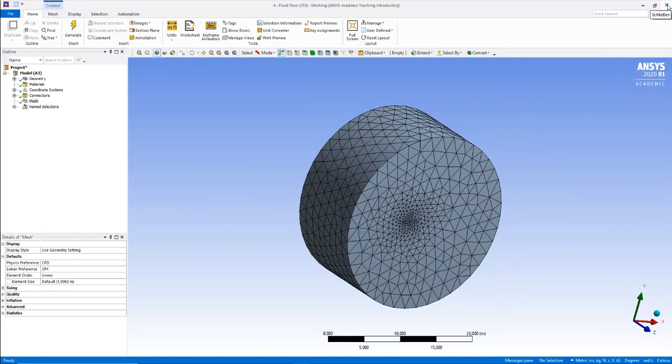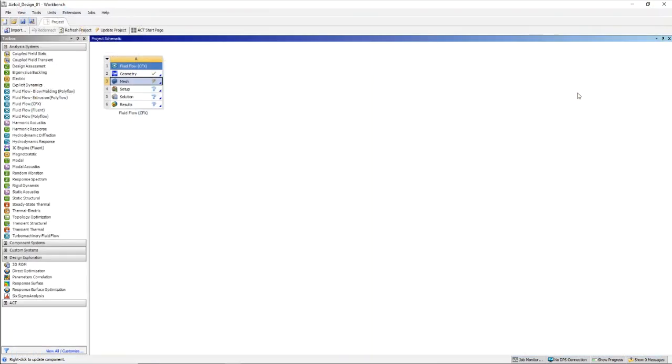Okay, and we're finished. You can close the mesher, and that's a small bug in ANSYS. There's no green tick, so you have to go to update again. In the meshing tool, I do not know why, but you always have to do it twice. And imagine it's a lot of data that has to be written on your disk, and you need a lot of memory. So take your time, let the computer work, don't click anywhere else too fast.